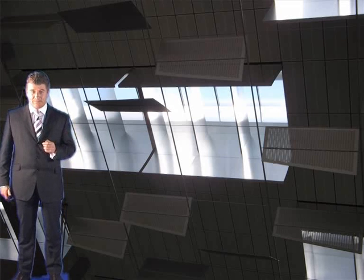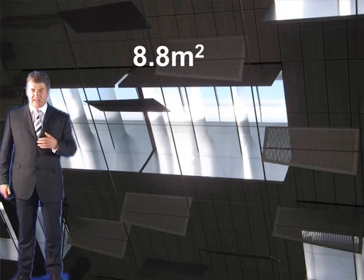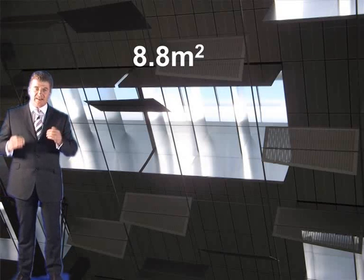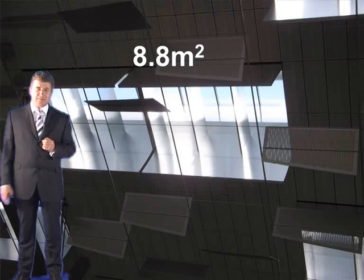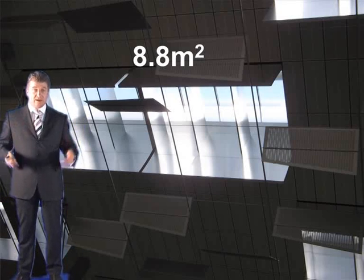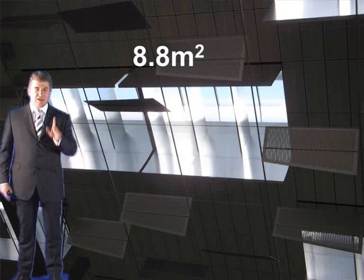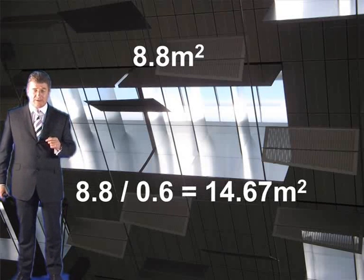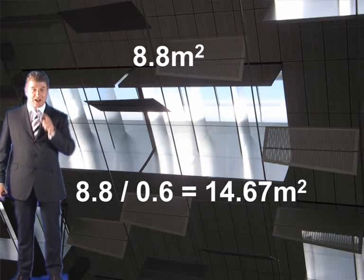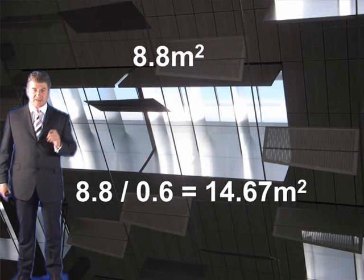Let's move on to step 7, which is determining the number of ventilators. Well, we know what total area of ventilation is required, 8.8 square metres. Now this is aerodynamic free area. In other words, you've got to take into account the efficiency of the ventilators. They're normally about 60% efficient, or 0.6. You're not going to get the whole area extracted. So if you divide 8.8 by 0.6, you get 14.67 of geometric area. So that's what you actually need in each reservoir, 14.67 metres squared of geometric area.